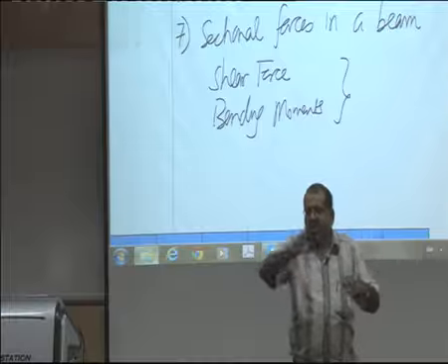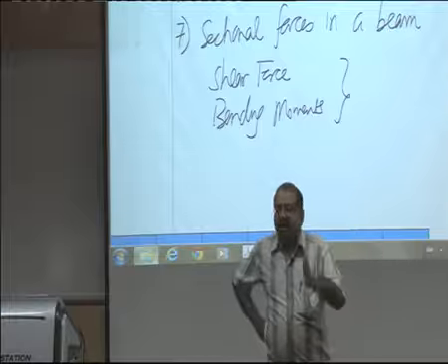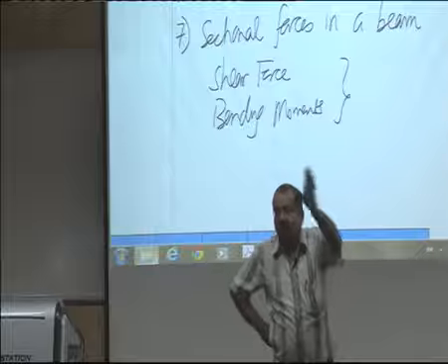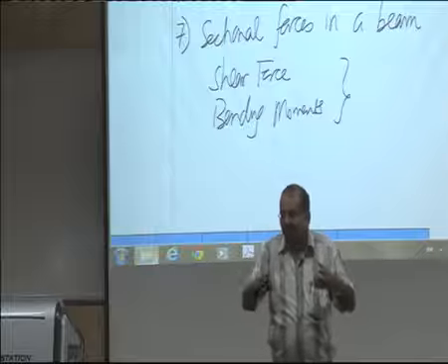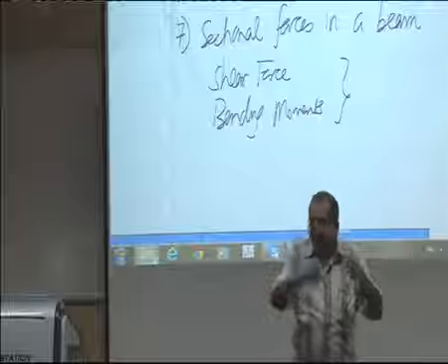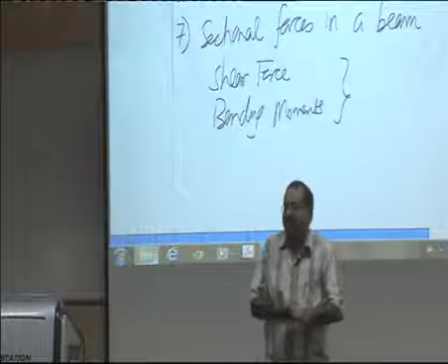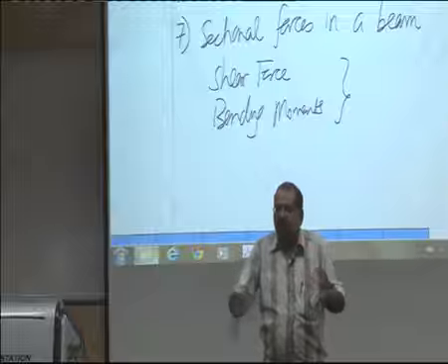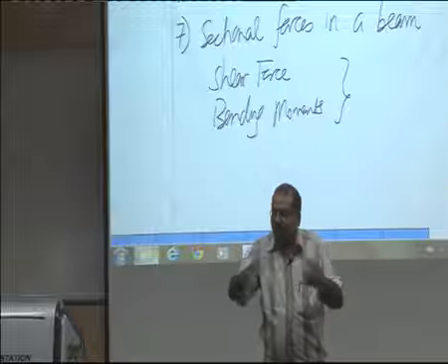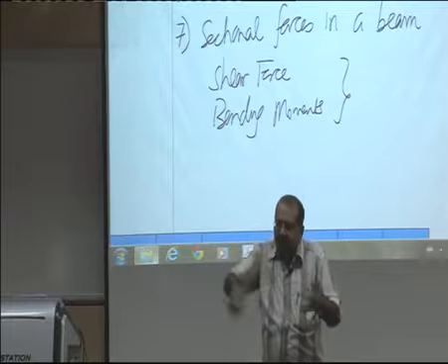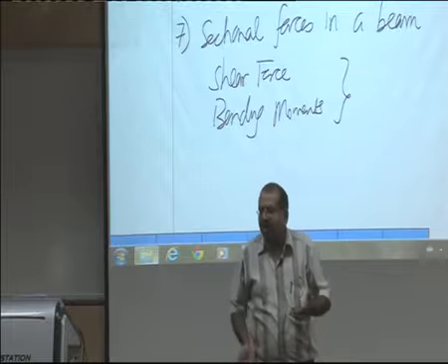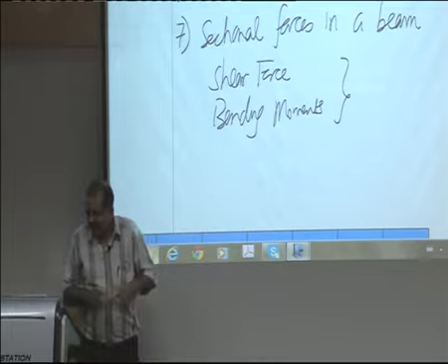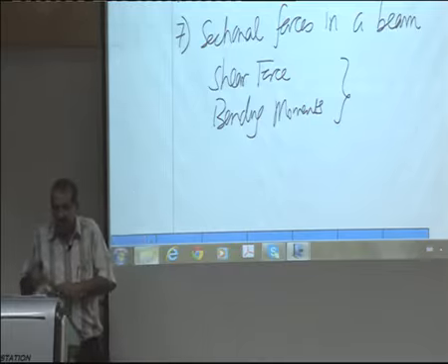And then also, we know that dM by dx is equal to V. So when shear force is 0, at that point bending moment should be maximum or minimum, or when its area is changing sign. That should be reflected in your diagram. But exact curvature doesn't matter. When it's a cubic shape or quadratic shape, as long as the overall figure is correct, it doesn't matter if you make the curvature concave or convex. It's not a maths course, so I will not be doing that. Well, some people do insist.